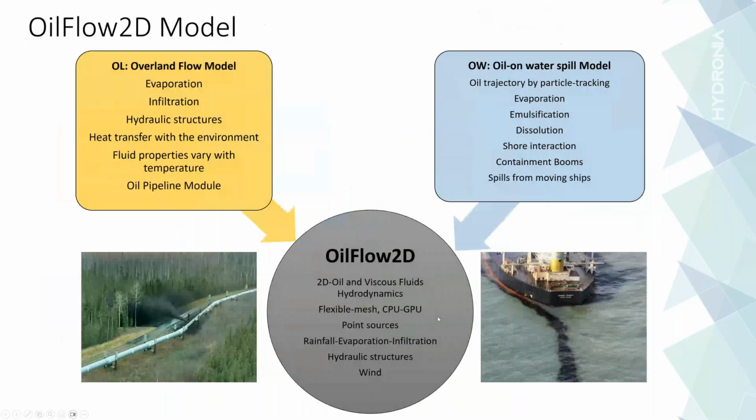Then we have the OilFlow2D model that has many of the features of RiverFlow2D in terms of the water hydrodynamics, but also has oil hydrodynamics. The oil hydrodynamics is divided in two parts. One is the overland flow model that also addresses oil weathering like evaporation, oil infiltration, hydraulic structures, heat transfer with the environment, and has also a new module that is the oil pipeline module.